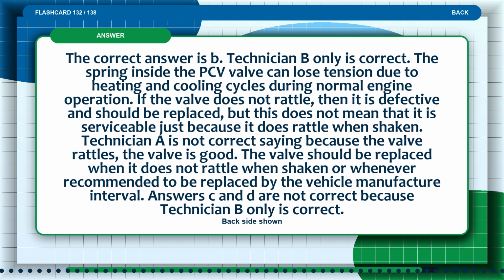Technician A is not correct in saying that because the valve rattles, the valve is good. The valve should be replaced when it does not rattle when shaken or whenever recommended by the vehicle manufacturer interval. Answers C and D are not correct because technician B only is correct.